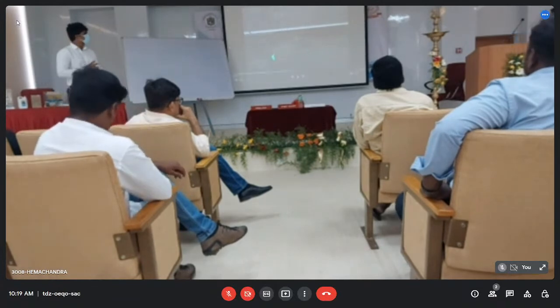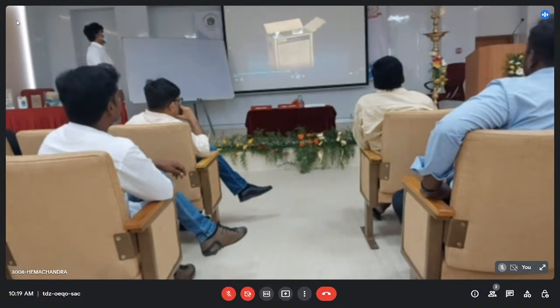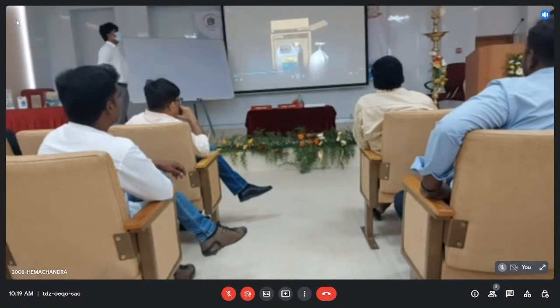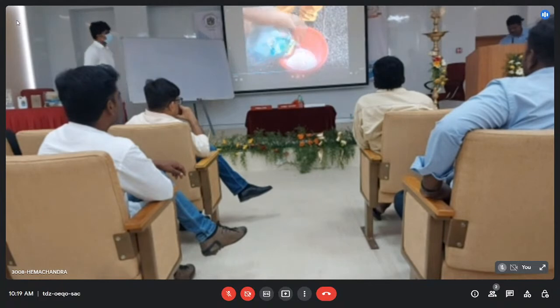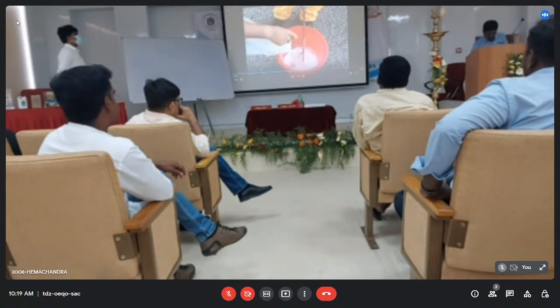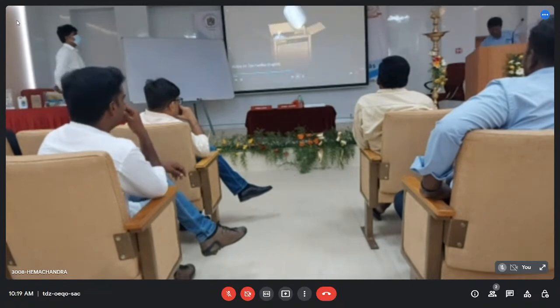Excess water. The surface should be in a saturated surface dry condition. Dr. Fixit Fast Flex consists of a powder and a liquid. Use the entire quantity of the liquid and add the entire quantity of powder.